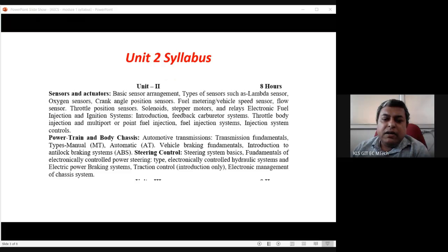So if the core is moving from left to right or right to left, the voltage in the coil changes. The more the displacement, the more the voltage. From left to right it generates positive voltage, and when it moves from right to left, it generates negative voltage. So is displacement a scalar thing or a vector thing?